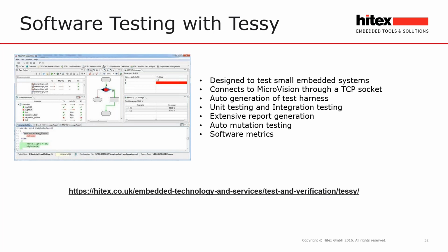Here we can analyze our C code. We can graphically set up test cases. We can do auto generation of the test harnesses. So it will generate the test harness, download onto the target, run the code, give you pass fail, and then generate all of the documentation.